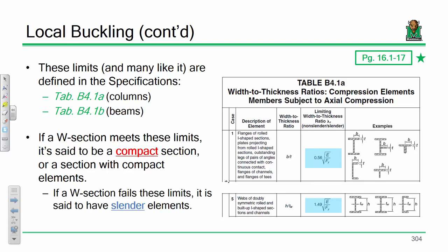You're actually creating one. In bridge land, that's very, very common for fairly long spans because you're customizing the shape of the flange and the web to meet your load demand. Whereas in buildings, the loads just aren't that big. You don't need that level of customization, so you just use shapes that are rolled. And believe me, there's plenty of shapes in here to choose from. So, yeah. Sound good? Okay.